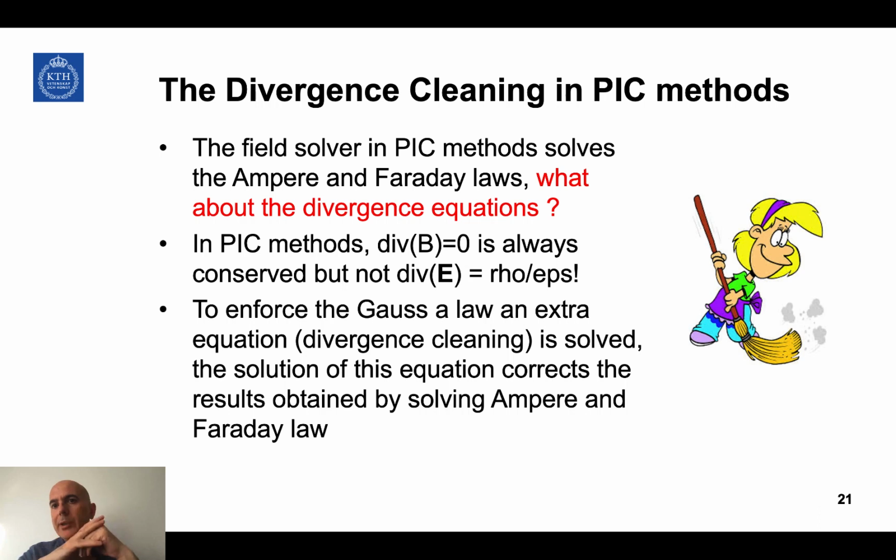So this is typically an important equation to solve because it guarantees the so-called charge conservation, that is, that the continuity equation for the charge density is satisfied. So it is strongly recommended that we always have this divergence cleaning, to satisfy these extra equations. This extra equation handles the electrostatic part, also the very high frequency phenomena. So if you want to have a highly accurate simulation, we need to have this divergence cleaning on.